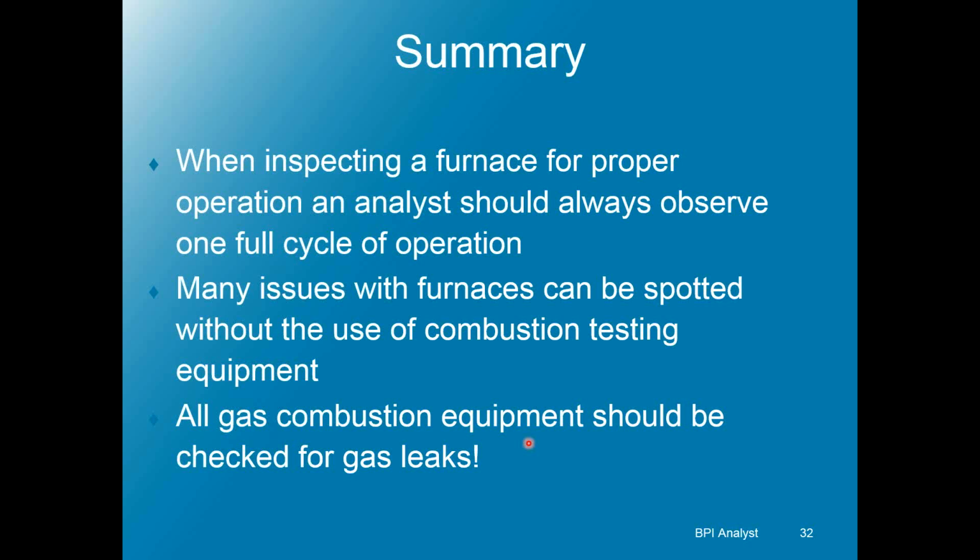So you want to inspect or view one full cycle of operation, start up to, and that doesn't just mean turn it on and listen to it, but actually watch it so you can see the flames. A lot of times you can spot issues with the furnace just visually from the flame rollout, the issues that I showed you before. But you always want to use gas leak equipment and combustion analyzers on gas appliances too, to double check them.